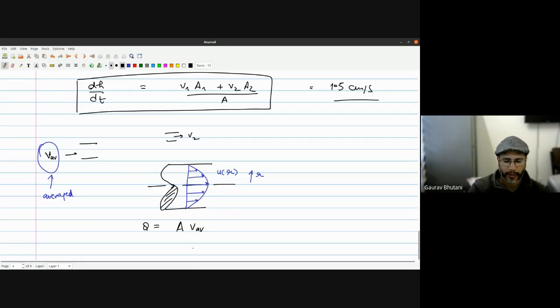So that's what we are using the average velocity for, getting the volume flow rate. Because in the control surface integral, that v dot n term that we have, there we need an averaged velocity. Okay. And if you were to calculate the volume flow rate using a proper integration in this pipe situation that I've shown you, then at different cross section areas in the pipe, the velocities are different.